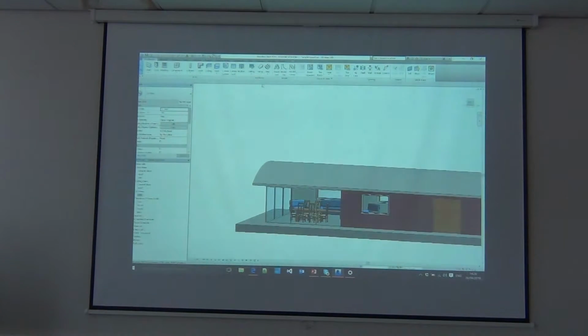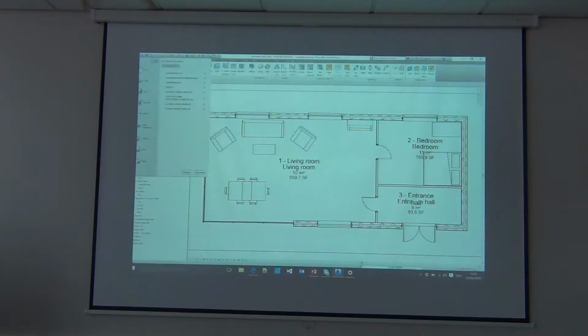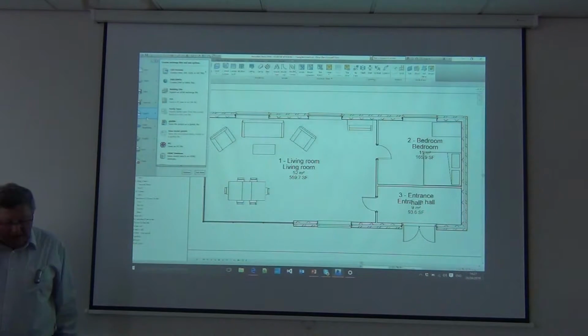Now, at the moment in Revit, when you use it, if I go back to the ground floor plan, because it's easier to see, if you want to export, I mentioned there was 2 ways that we could create the Cobie for this project. We could get a plug-in from Revit that will do that, and we'll just directly write it out as Cobie, or we can write it out as IFC and then convert the IFC to Cobie. And I'm going to do both of those things in a way. So here's the first one. If we want to write it out as IFC, you'll find on Revit under Export you have, lo and behold,